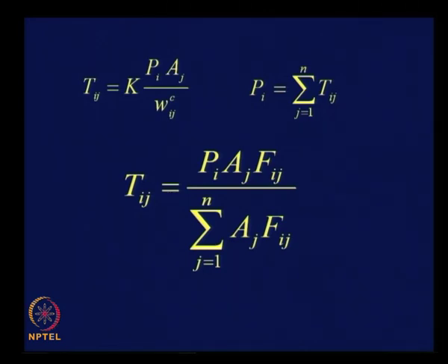This is a very simple formulation of gravity model without consideration to the zone to zone adjustment factor, which is Kij. And we need to understand that we have introduced one constraint here, namely Pi equal to sigma j equals 1 to n Tij to get the final equation for the gravity model. So, rightly we can call this gravity model as singly constrained gravity model.